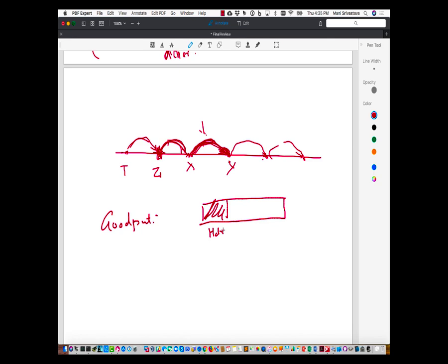So the actual good bits going across is the rate at which the channel is operating, let's say a megabit per second radio, multiplied by some fraction f, where f relates to, at the very least, the payload divided by the overall length. But then you also have a probability factor because the packet has a certain chance of being dropped. And so you have to look at the expected number of packets which are going through. So for every bit that I need to send across, how many bits do I really need to send on average?